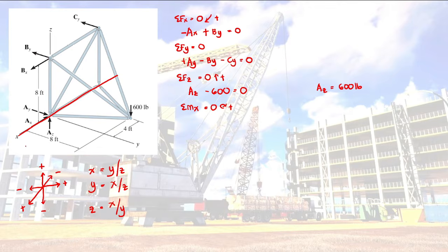So, bakit ganyan? So, pag ito yung axis natin of rotation, say maglalagay ako ng force here. So, Fx. Would this rotate? And this is yung line of rotation natin. It would not rotate kasi nasa plane of X ka. So, for here, our AX would not rotate. BX also would not rotate. How about our AY? Would it rotate? No also, kasi nasa line of action din siya. Wala tayong magiging moment arm for AY. Also AZ, it would also not rotate because it is at the x-axis.